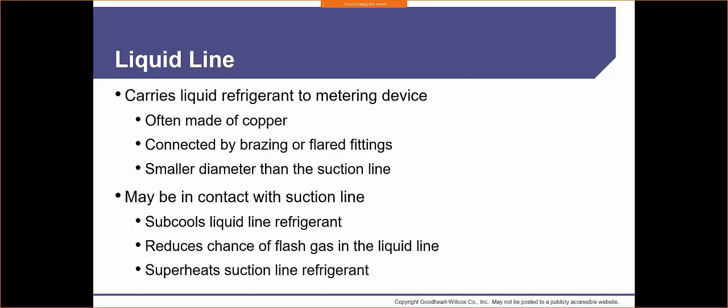Okay. Like I said, there was some talk of people using aluminum. I don't like aluminum line sets. I would stay away from them. I've seen videos of them exploding. So if anybody suggests to put anything on to carry refrigerants other than copper or stainless steel, I would run away quickly. So how do we connect copper?